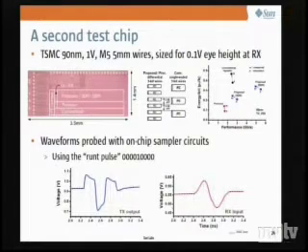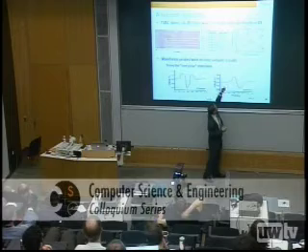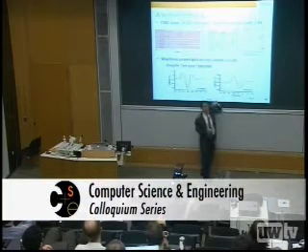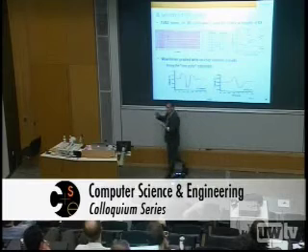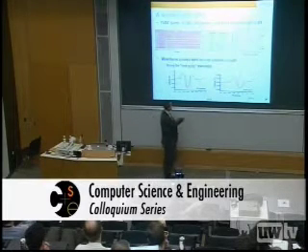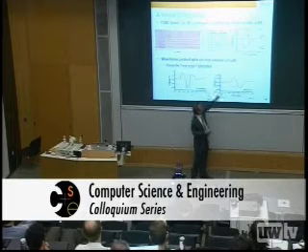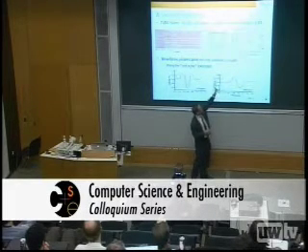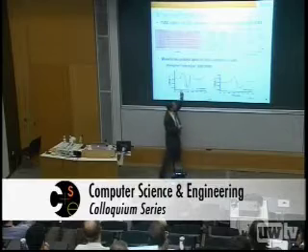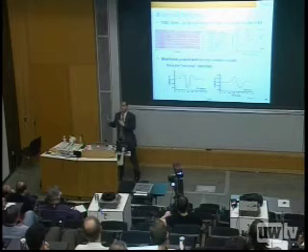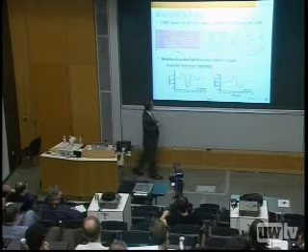And the plot on the right, which I can't reach even if I jumped, is performance versus energy again. The pairs of points are the simulated versus measured for the chip that came back. And the black one on top are repeaters of standard conventional CMOS form. And the dots underneath are the versions that have the capacitive driver in red, the return to zero signaling in the middle, and the DDR version on the right. You can see that we have significantly more bandwidth for not that much more energy. So it's a reasonable trade-off that you could perform for these sorts of circuits.